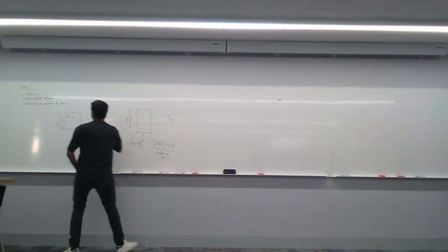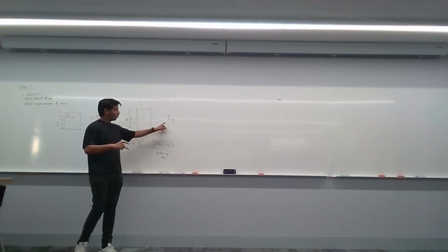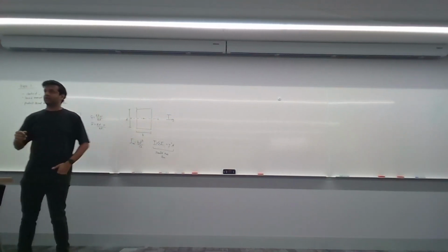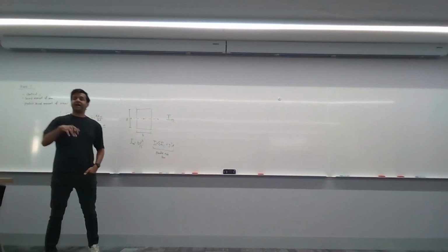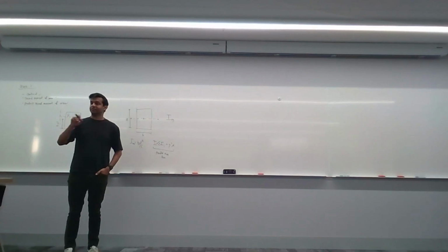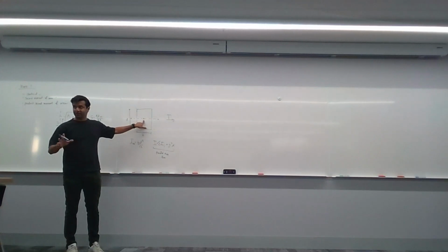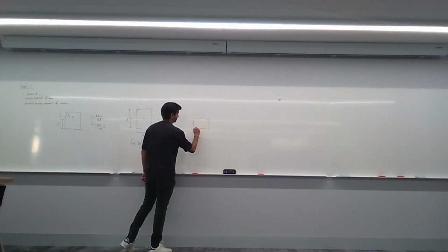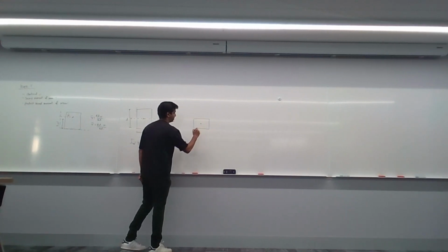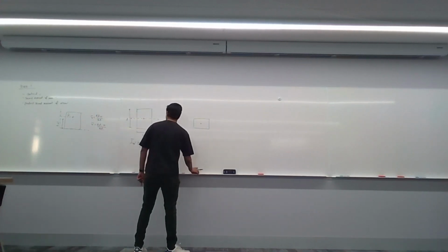Ixy. So that's this last part here, which is the product second moment of area. Can anyone tell me what Ixy is for this rectangle? 0? Okay. So we know that Ixy for a rectangle is 0 when Ixy is taken about the centroid, right? Can anyone tell me for this rectangle here, Ixy is still 0? Yeah? Okay.